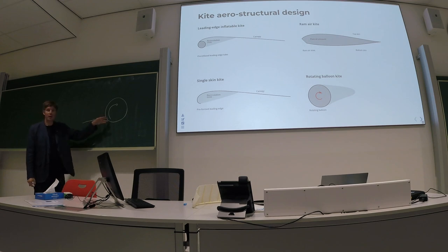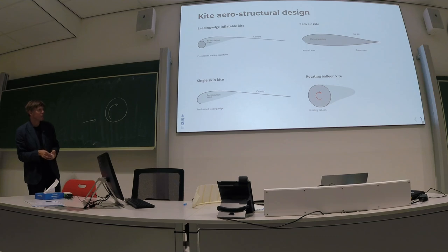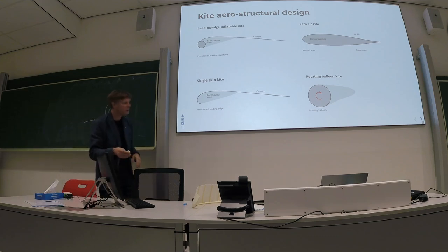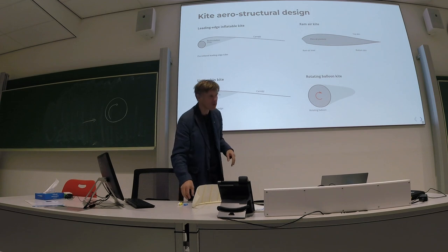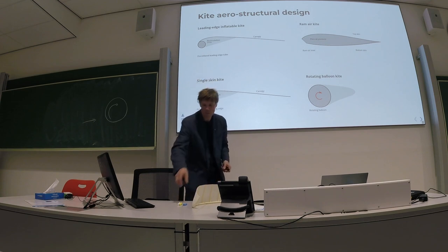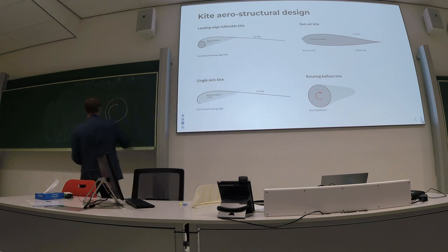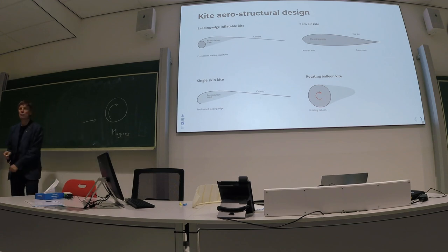If the cylinder does not rotate, if you take this piece of chalk, in an airflow it would not create a lift force. But if it does rotate, it creates a lift force. That's an aerodynamic effect, actually an implicit aerodynamic effect, and it's called Magnus effect. And that is actually used for ship sailing.